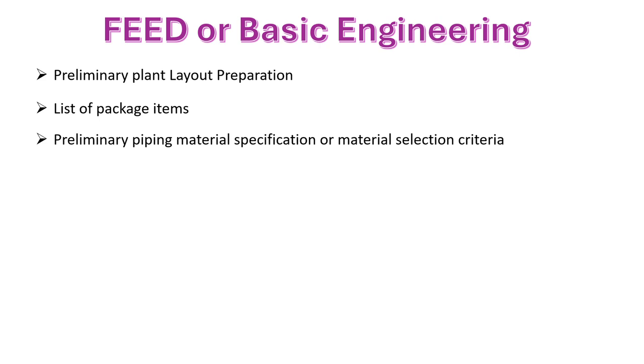Other process water lines, which are critical in terms of plant operations, need to be taken care of with a suitable material of construction like SS304 or SS316L. For corrosive material, we have to select piping MOC such as lined material, Hastelloy, or exotic material as per the process specification. That needs to be taken care of during this basic engineering.